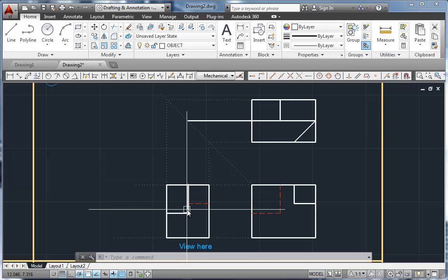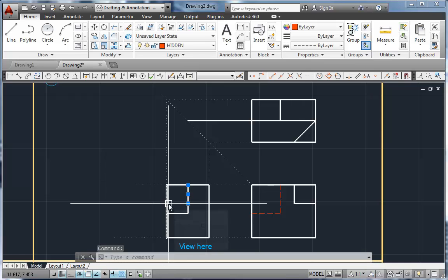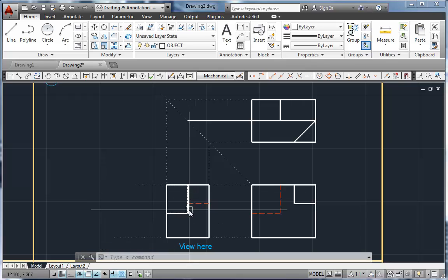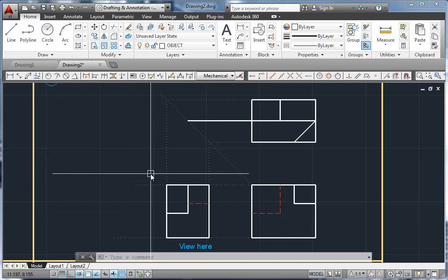So when you have a visible line and a hidden line in the same place, the hidden line goes away. Okay? So I'd see this piece of hidden line, I would not show that one. Leaves the reader possibly slightly confused in this situation, but nonetheless, that's the rule. We can't show duplicate lines here. So this is actually my finished left side view. Okay? All right, let's zoom out.